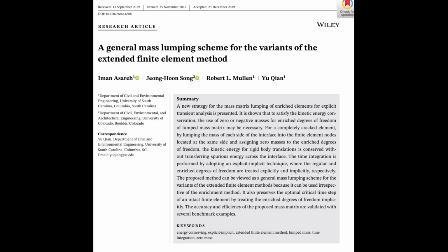Okay, so to see why they do that, we need to quickly touch on how mass is represented in these simulations. Engineers use something called a mass matrix. Right, to show how mass is distributed. Exactly. Now, for speed, especially in these super fast dynamic simulations, they often prefer what's called a lumped mass matrix over a consistent mass matrix. A lumped matrix. So instead of being spread out evenly, the mass is concentrated at specific points, the nodes, making the math quicker. You got it. Think of it like, instead of weighing every single tiny bit of a structure, you just estimate the weight at the main connection points. Much faster. Makes sense. But.